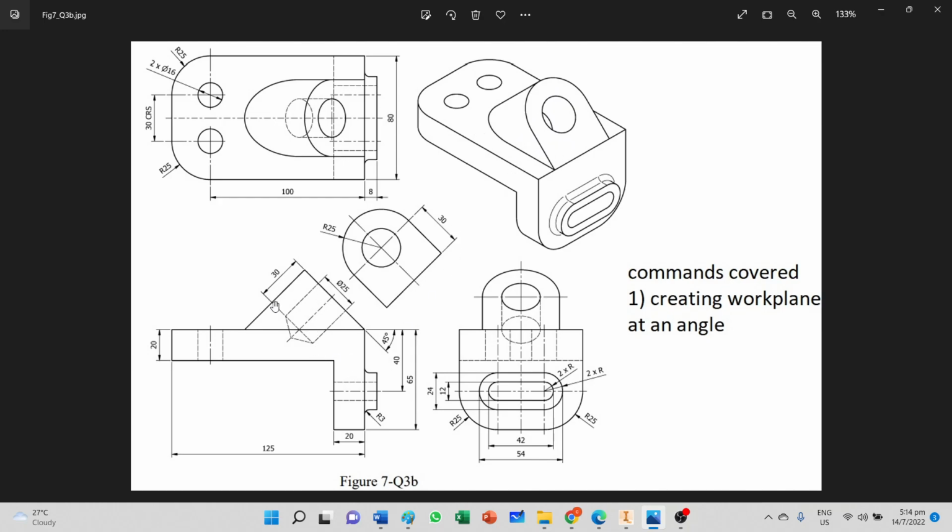Now this one here is a blind hole, and as you can see, there is an angle over here, the triangle over here. So we need to have that done using the hole function. Then there is a slot with an emboss and a radius that goes all around it. What's the radius?